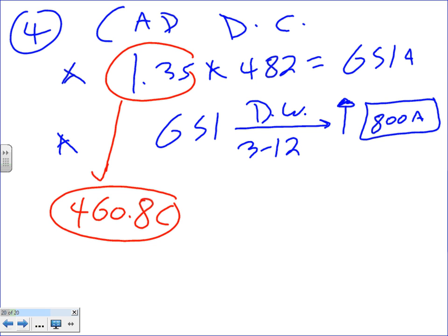So they did all the math for us, guys. What I've done with you for motors, they already did the math. So this table is really nice. You can use it as a standard table. For example, I have a capacitor, but the table doesn't go higher than 125. Can you guys see that? If you have a 125 kVAR, the full load amp is 150. Do you know how they came up with 150? They take the 125 divided by 1.73 and 480, like I did. The size of the conductor is 3 aught, the overcurrent protection device is 250, and the disconnect is 400.